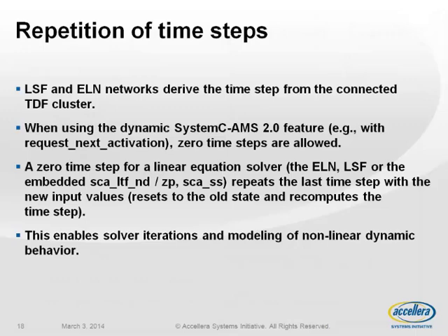Otherwise, you would not be able to ensure that the SystemC simulation would continue. Now, in SystemC AMS 2.0, we allow 0 time steps to be able to re-evaluate dynamic equation systems based on an updated internal state. This is automatically taken into account by the linear equation solver for the LTF functions, the state space equations, the LSF, and the ELN solvers.